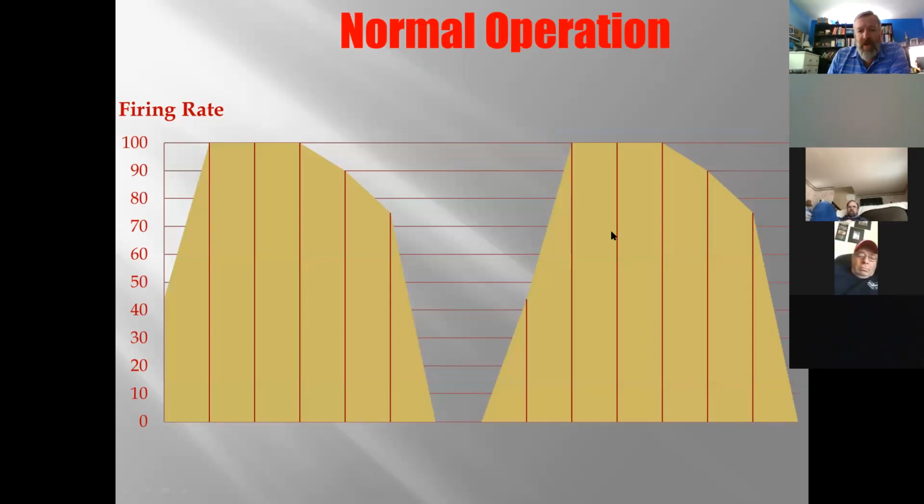So we talk about slowing the boiler down. In normal operation, the boiler's sitting there in the basement and says, well, you bought a 200,000 BTU boiler, so I assume every time you call me on, you need 200,000 BTUs. It doesn't know whether you have 1 zone or 8 zones. It doesn't know if you bought it because there's a party shower and you need 200,000 BTUs for a 120-gallon indirect, but you really need 50,000 BTUs for space heating.